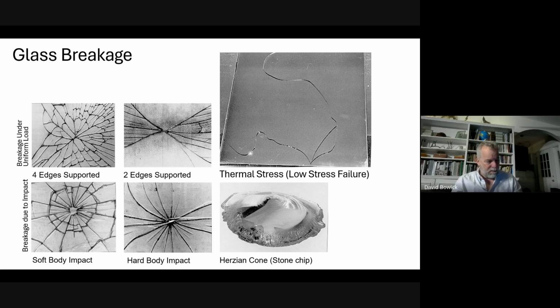My most embarrassing thermal crack story is I owned a pub in Scarborough at one time, and while I was renovating the pub, I didn't want people to see in and see that there might have been tools to steal. So I taped black garbage bags all over the inside of the window. South-facing window, cold day, but bright sunshine, black surface. The sun hits, absorbs the black surface, warms up the window on the inside, cold from the outside, and I broke my front windows.